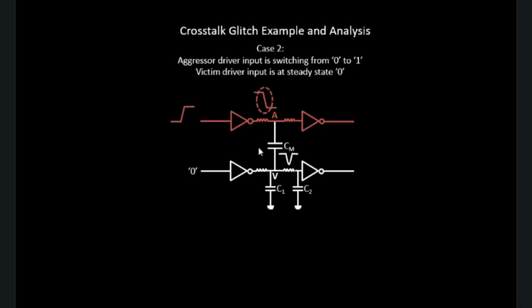In this process, since this is a bucket which is completely filled, but in a reverse direction, and you see a hole at this bucket, the charges which are present over here also try to discharge through this leaky bucket, and then through this inverter, because this inverter is strong enough to take this charge and discharge it. So this is the way you see a reverse glitch.